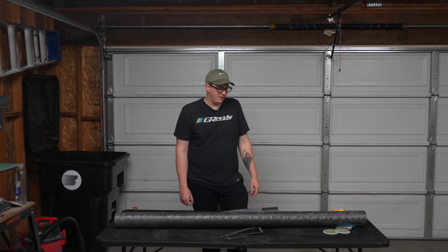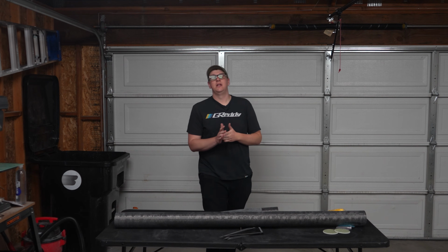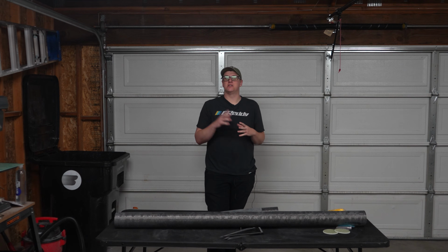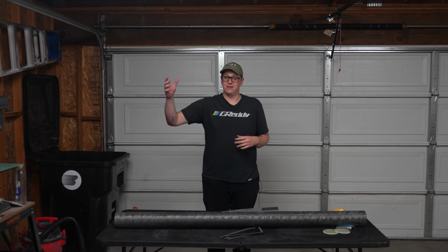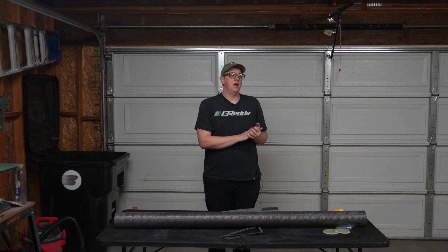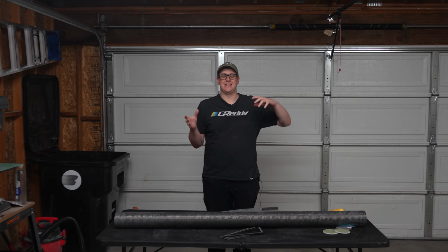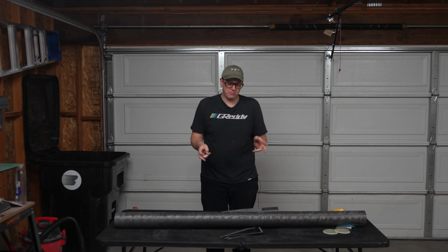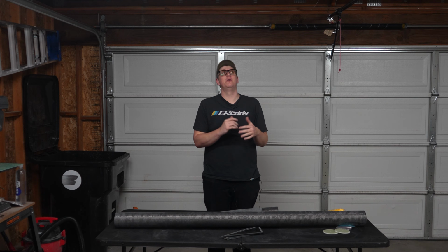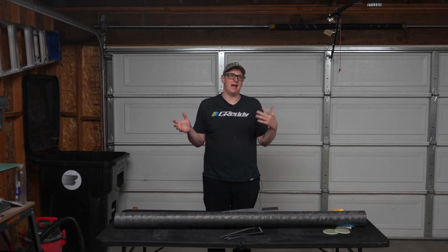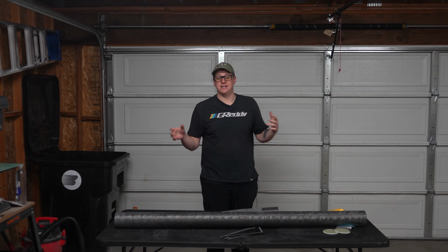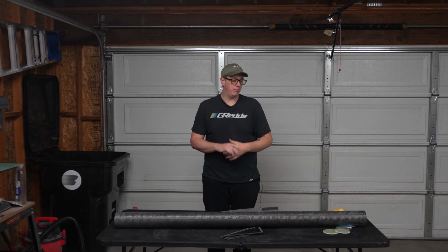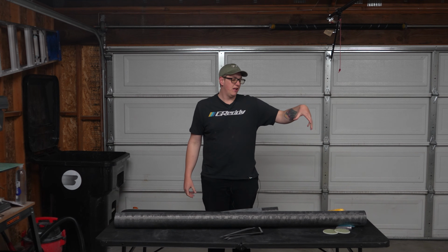And I received some information from Chris Short, csrocketry.com, that he has flown a few N1000 minimum diameter projects that went pretty drastically over the simulated flights, because his theory is that the base drag is still minimized. Even though the motor has stopped burning, the motor still burns for a decent amount of time, just not as powerful. It's just not outputting a ton of thrust, but his theory is that the flame front and smoke and everything still being there is still drastically reducing the base drag.